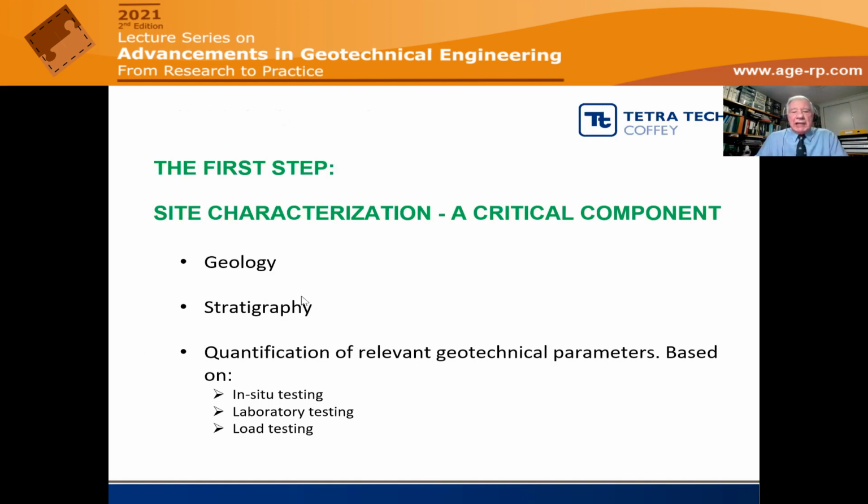We need to understand the stratigraphy, so we would do various types of boring and in situ testing. And then we need to quantify the relevant geotechnical parameters. And that's usually done on the basis of in situ testing or laboratory testing or load testing or a combination of all three, ideally a combination of all three.